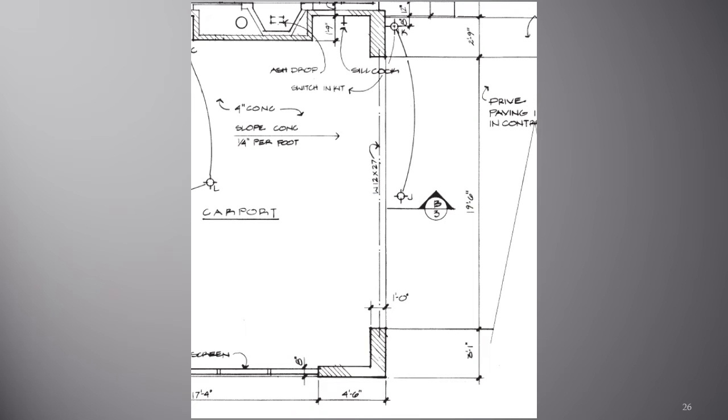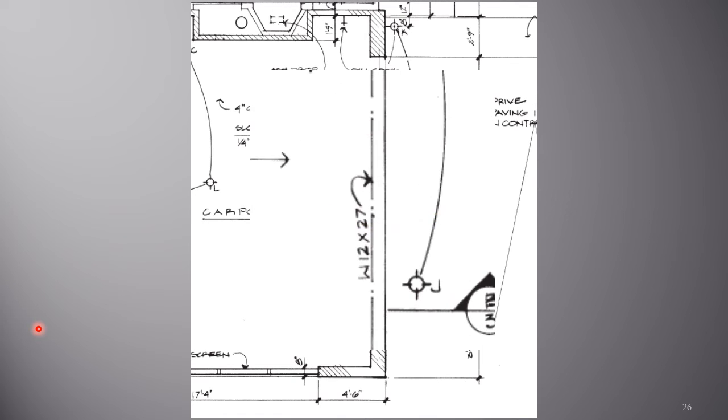Now, if we take a look at the floor plan from Brick Veneer 1, we see in the carport this call out for a wide flange beam, and that tells us that we want a W12 by 27 across the opening of the carport. Why? Because for a 12-inch deep beam, this would have a greater load carrying capability than a timber joist for this very long open span.